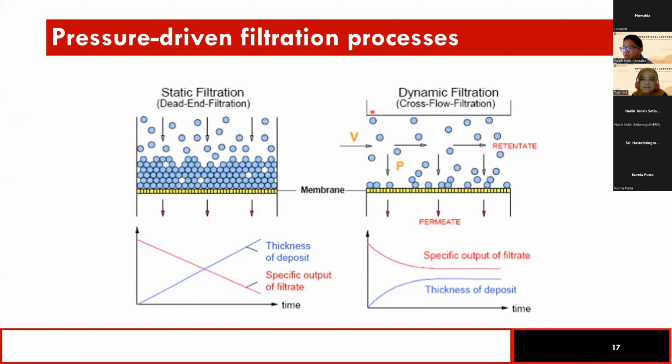Okay. So another picture is this. So static filtration or dead-end filtration looks like this. And as time goes by, all these materials will deposit on top of the membrane, and this will affect the filtration process. And eventually, it will just stop.